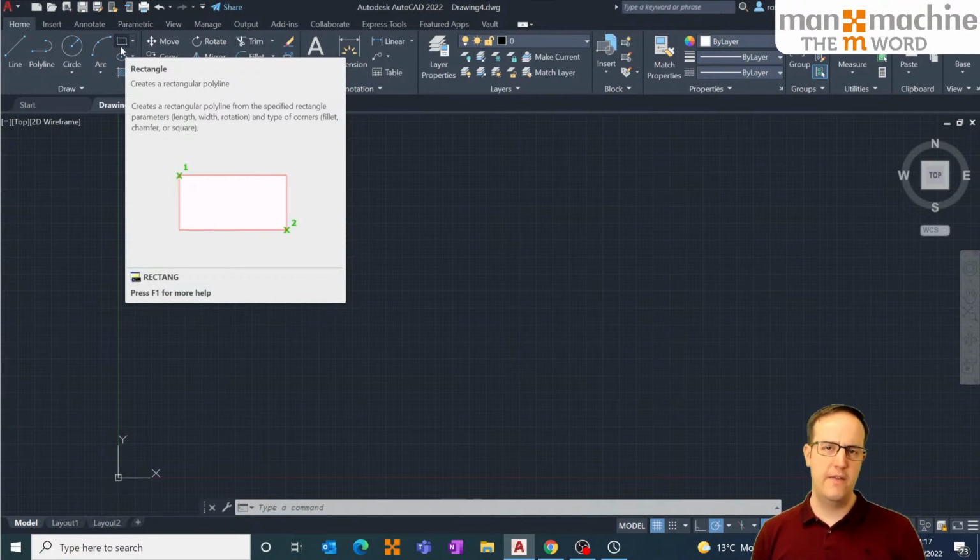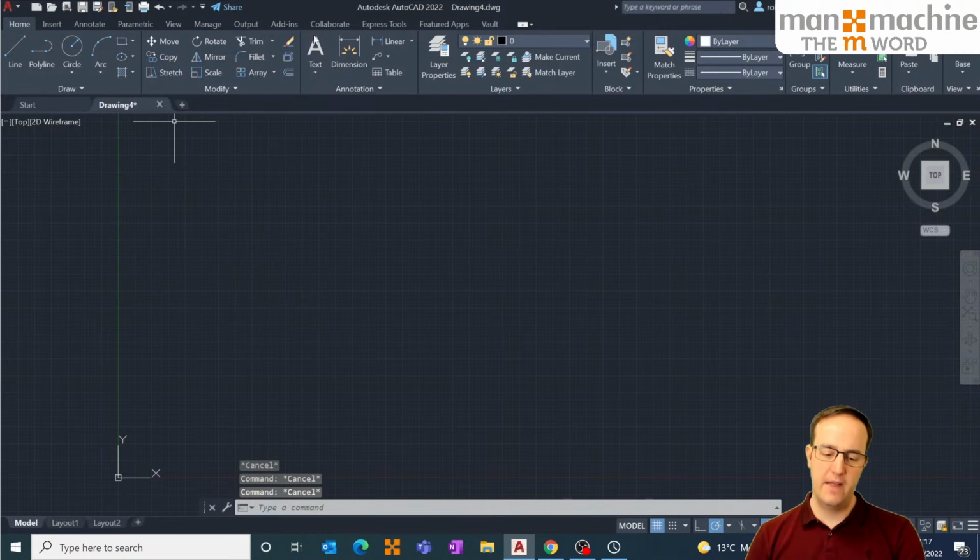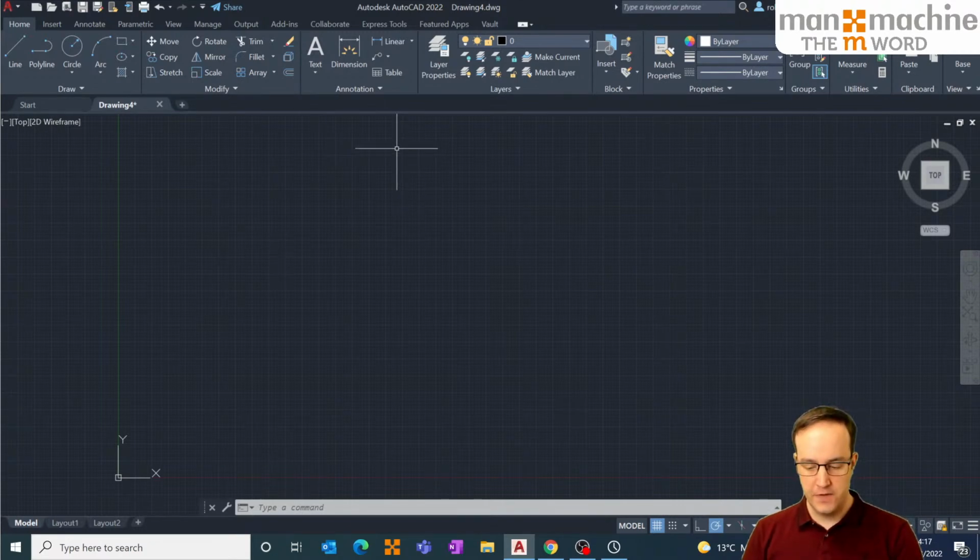But there's a lot of you out there that have been using AutoCAD for longer, and I can guarantee that there'll be someone watching this video that has several dim styles, several text styles that they've set up for specific text styling on their paper. You don't need to do that nowadays in AutoCAD. You can have a template with one annotative style that controls what is visible, what isn't visible, and what size. So let's very briefly demonstrate it, explain it, and then we'll be done.